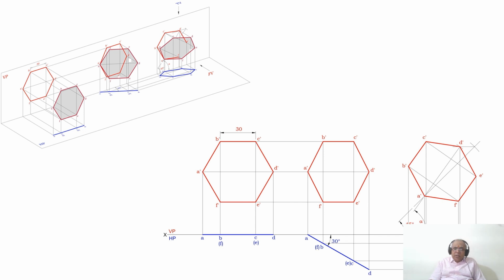So ultimately, how do I know that my drawing is right? You can see that the diagonal passing through the corner on which the lamina rests is inclined at 45 degrees to HP. Since you have been given the true inclination and the length you have is the apparent length, I cannot transfer this directly. So in such a case, I need to find out the alpha, which we have already explained.